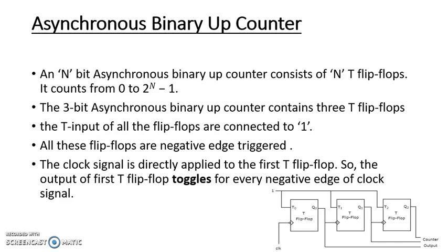If you see the block diagram of the asynchronous binary up counter, only the first flip-flop is connected to the clock input which is to be counted, and the remaining flip-flops, the second and third, have their clock inputs connected to the state change outputs of the previous flip-flops.